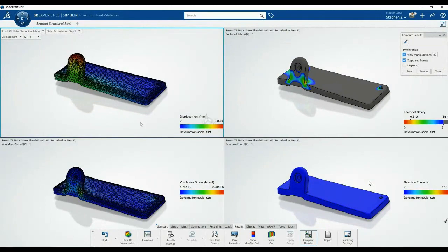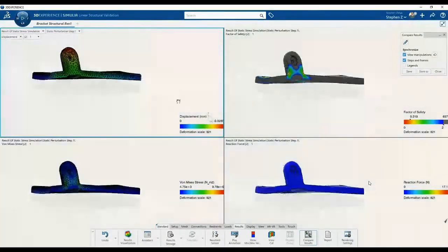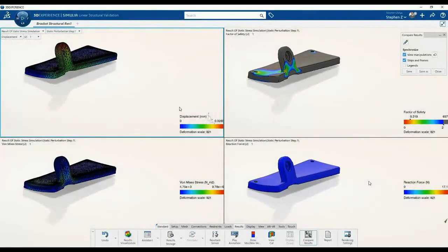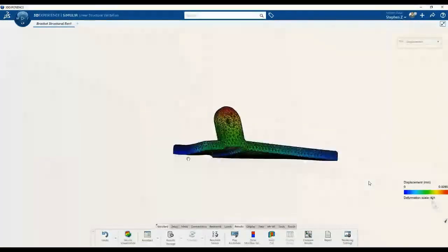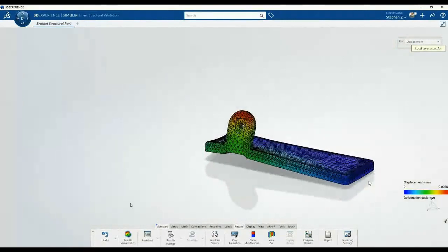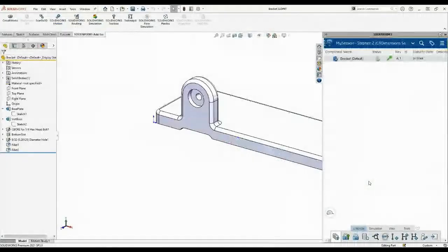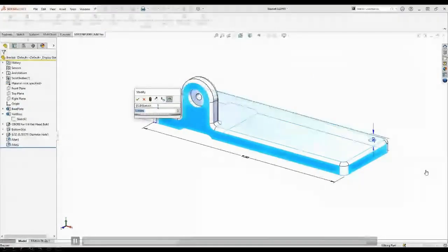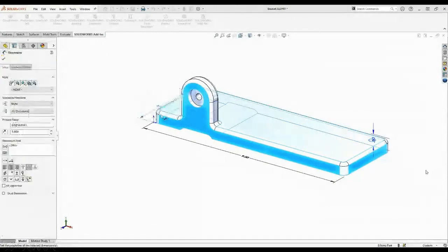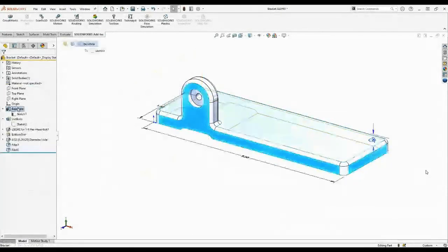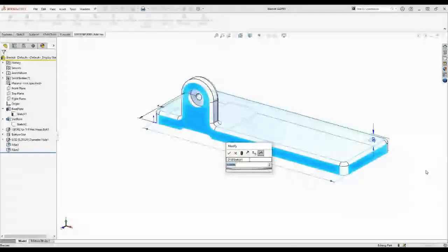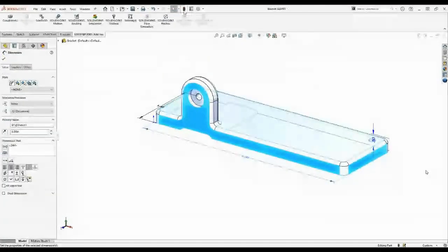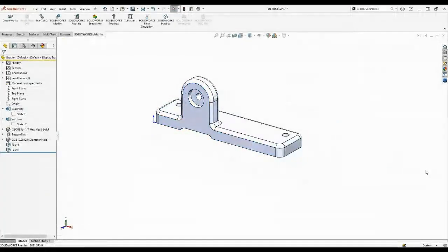So that's the original revision. This is revision 1. In SOLIDWORKS, the revision naming convention is A.1, and then we go to B.1. I called it revision 1 and revision 2, but we can set the naming options however we'd like. In this case, we're on revision A.1, and we're going to reset this back to the original geometry. So revision A.1, or revision A, is our baseline control. So we're going to rebuild that back to our original geometry.